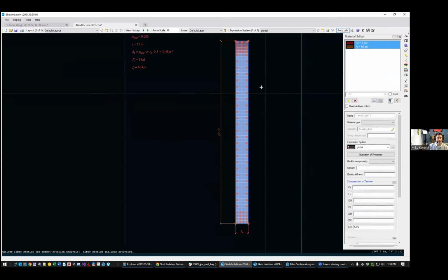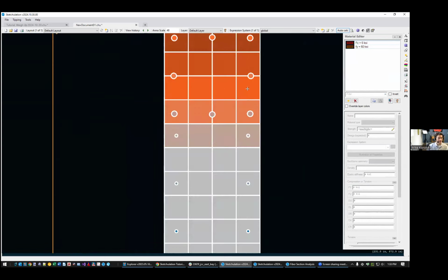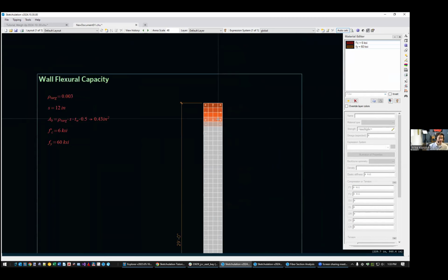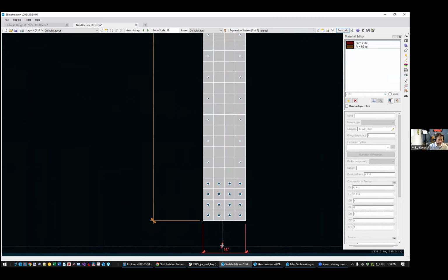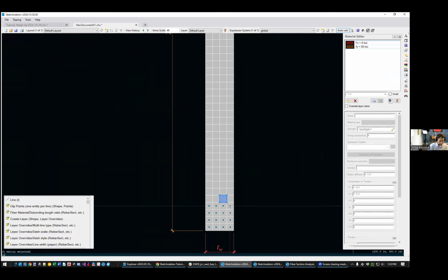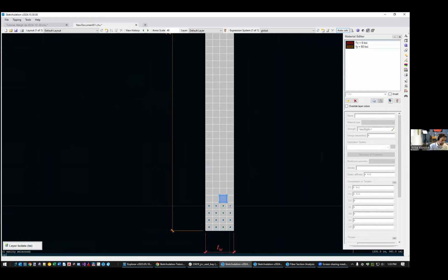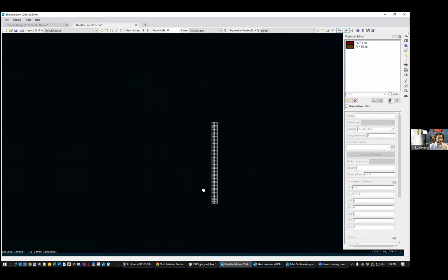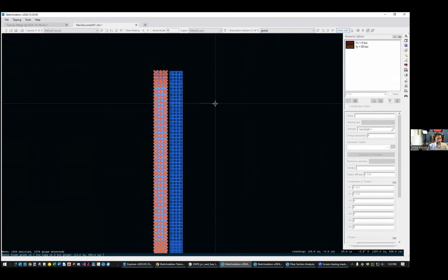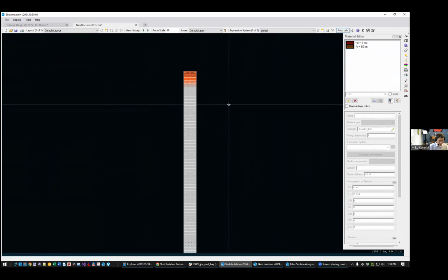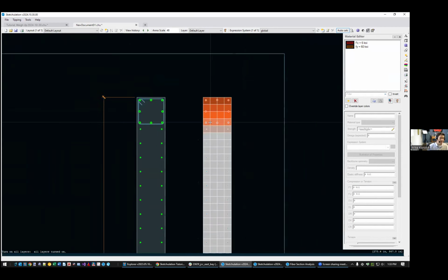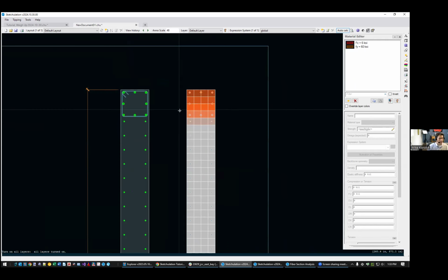It creates shapes in the drawing with those colors that you were seeing in the other image, and they're on a specific layer. So I'll isolate that layer, and then I can move them off to the side, or delete them if I want to. So I isolated them, move them off, and I can just keep them there if that's helpful for me for a plan checker or whatever.